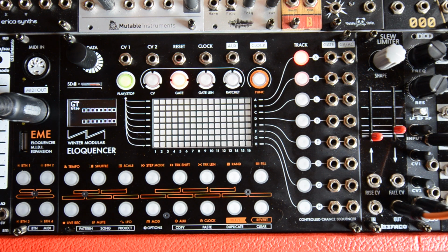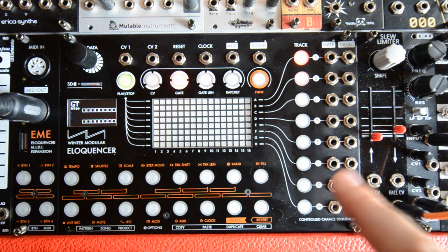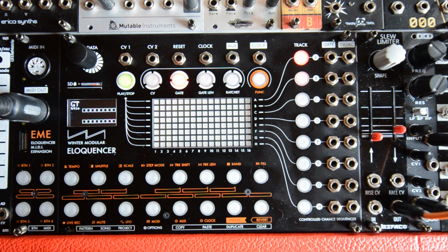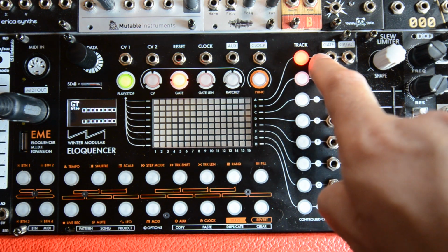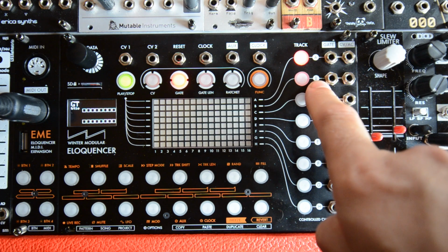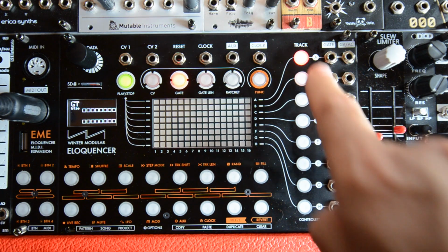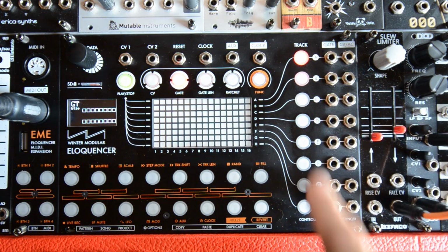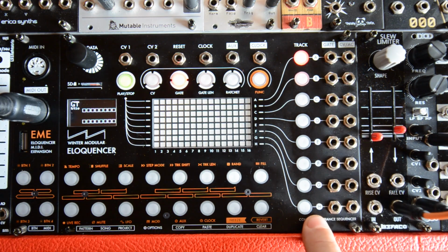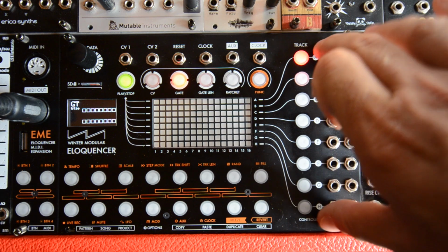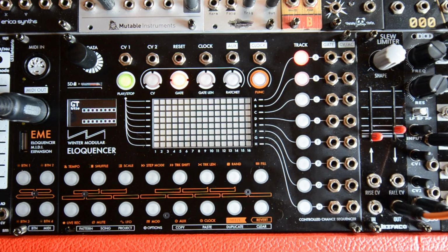We can use the tracks in different ways related to the MIDI channels and the type of message. For example, if we put the same type of voice message in track A and track B, and we put the same channel in track A and in track B, we will have two voice polyphony. We can go up to 8 tracks pointing to the same channel, so we will have 8 voice polyphony. This is not the main purpose of this sequencer, but it can be done.